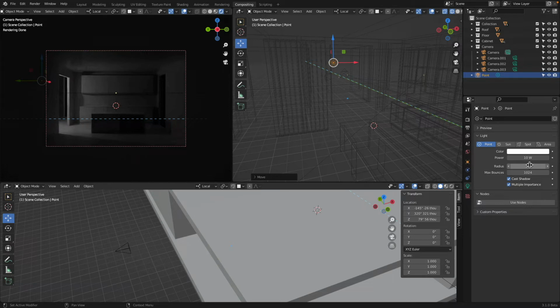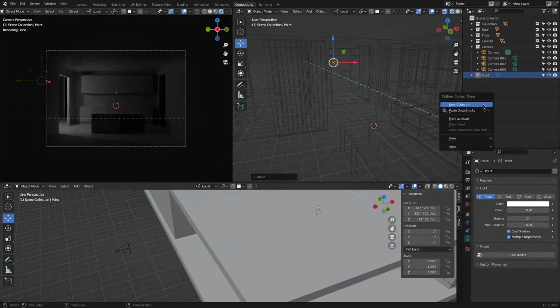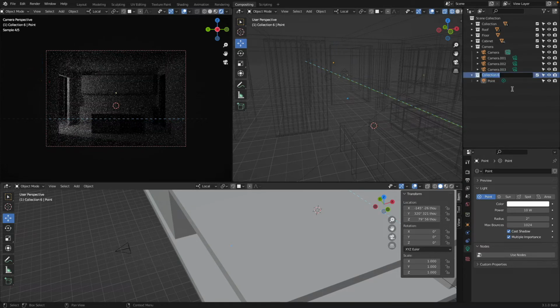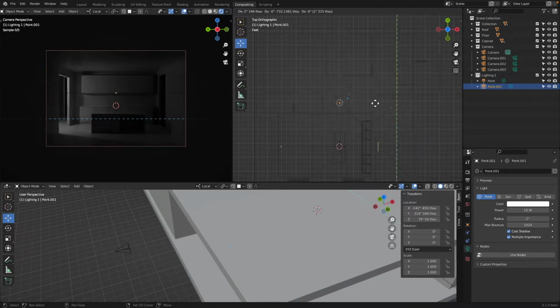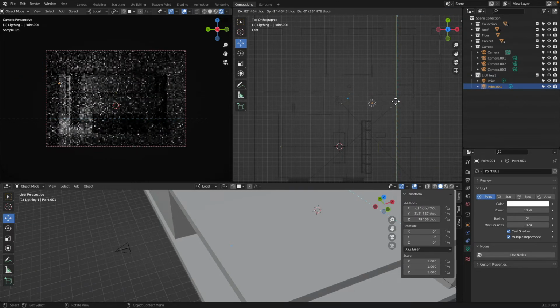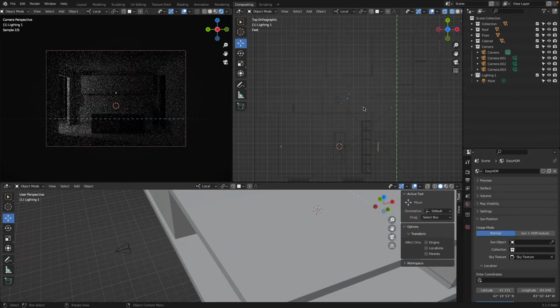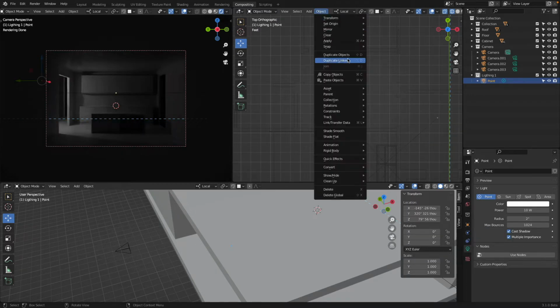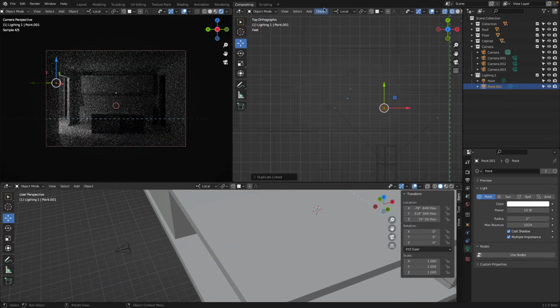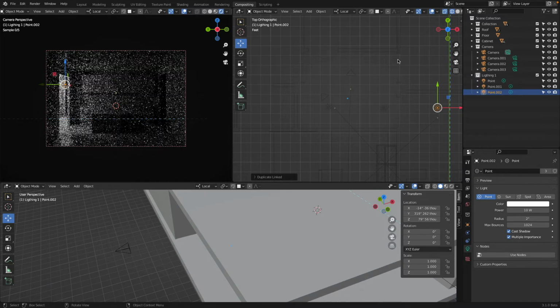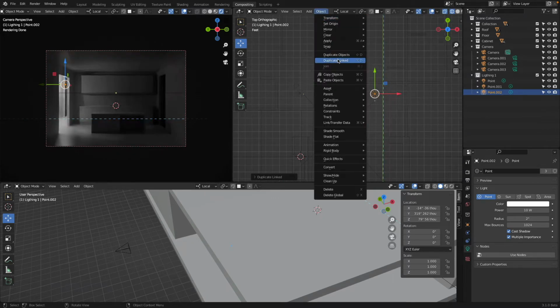And that's how you create, for example, sharp or soft shadows with a point light. Also here again, I say lighting, maybe lighting idea 1. And then I can, for example, select this, put this somewhere else, Shift D to make copies. I will delete these 2 lights, select this one, and then I will use this command here, duplicate linked. And one more time, duplicate linked. And one more time, duplicate linked.